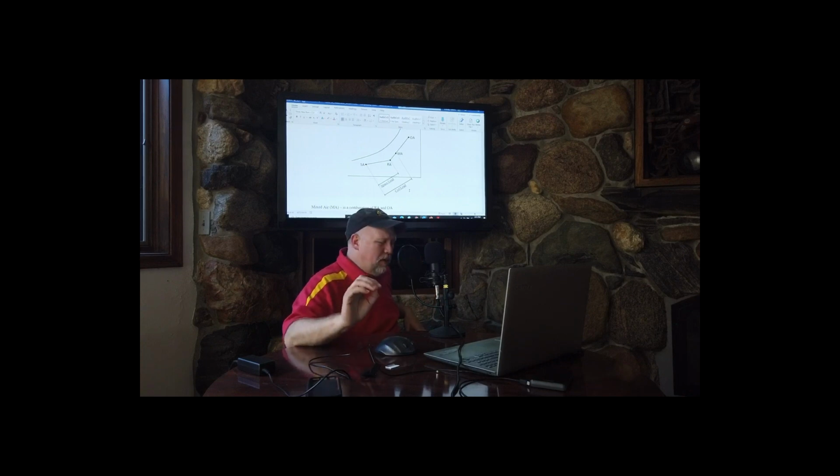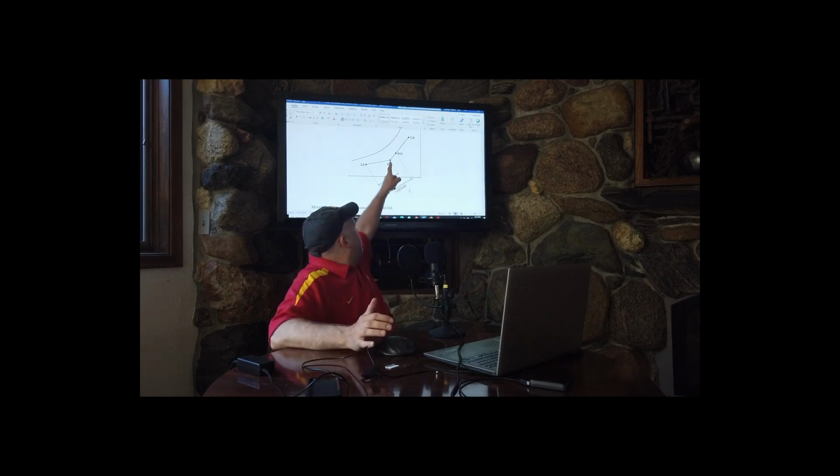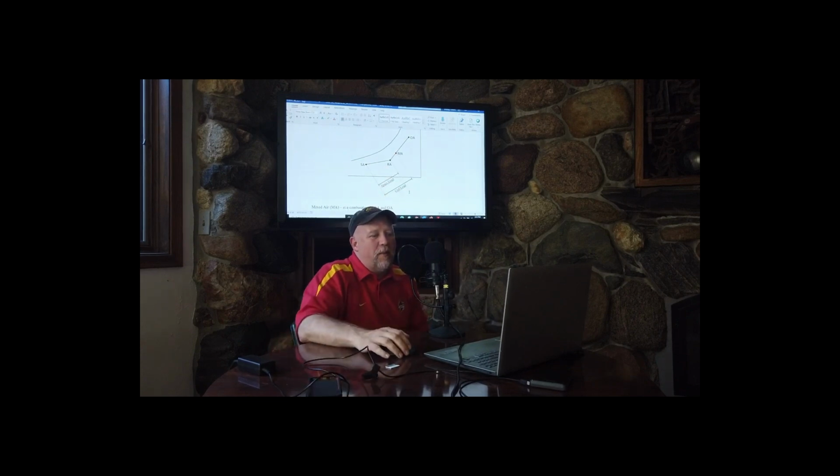You take, of that 23 degrees, if it was 20% outside air, that is 20% of 23, and that is exactly 4.6 degrees. So to the return air, we will add 4.6 degrees, and that will make it 76.6 degrees and go straight up to this line, and you have your mixed air point, and you can look up all the rest of the properties.